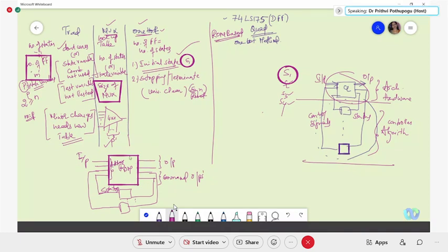This is programmed sort of thing. And as we know, any address line cannot be left vacant. I think we have seen this in the earlier DSD 1 also, with ROM and RAM, where any address pin or any address information cannot be left open or undefined. So undefined inputs are not supported by your ROM.